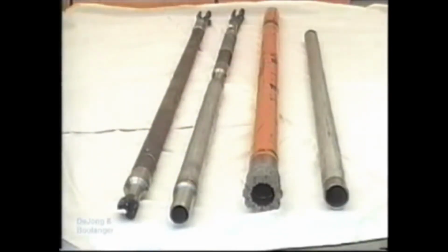Some systems, such as the Christensen 94 pictured here, can perform multiple tasks such as drilling, coring, and sampling. Wireline retrieval systems expedite coring by removing only the full inner barrel from the hole, thus retrieving the sample while leaving the outer barrel and drill rods down the hole.